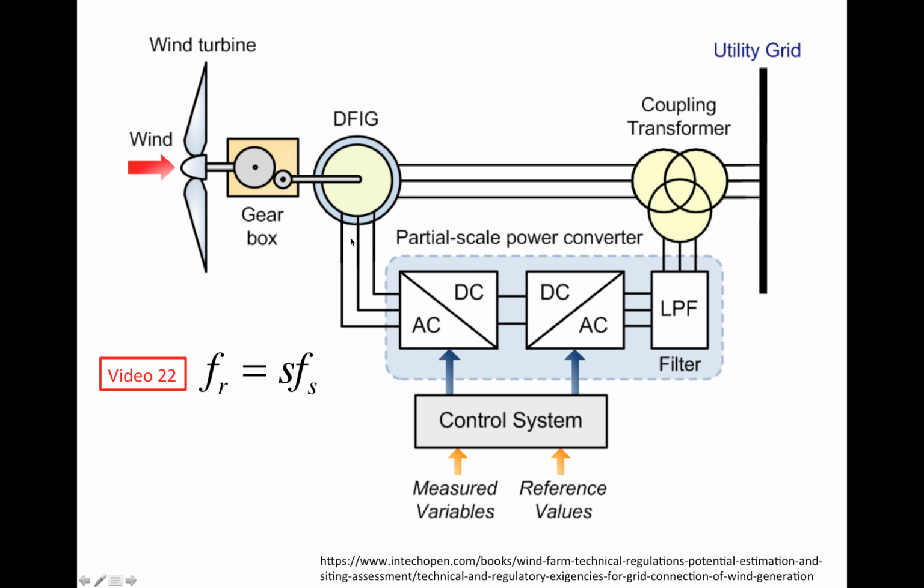Right. That's this part of the wiring. This part of the wiring is provided only by the wound-rotor induction machine. For a squirrel cage, you don't have these 3 wires coming out of the rotor. But by using a wound-rotor induction machine, you have these wires coming out of the rotor now, right?